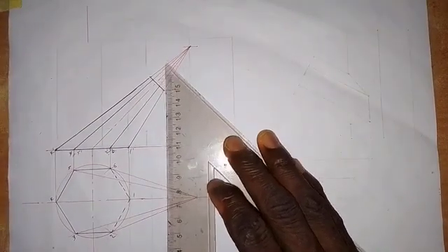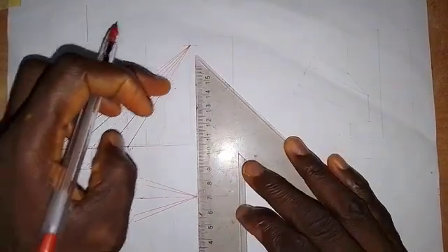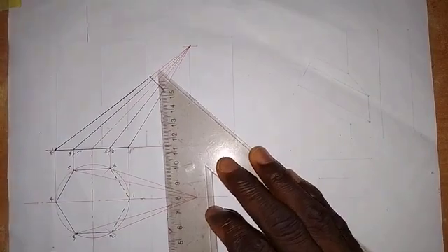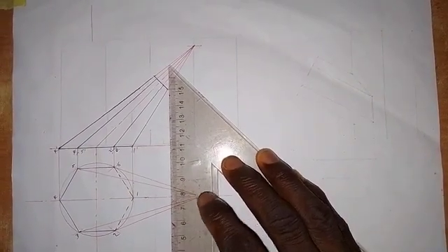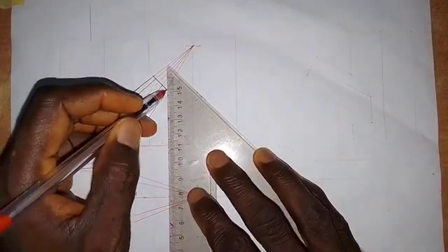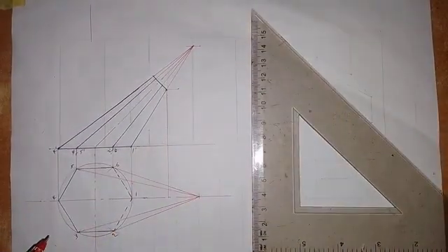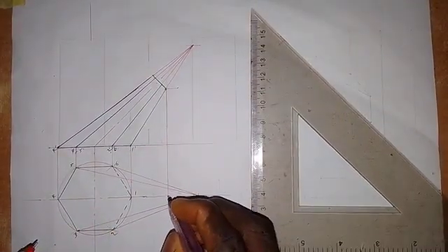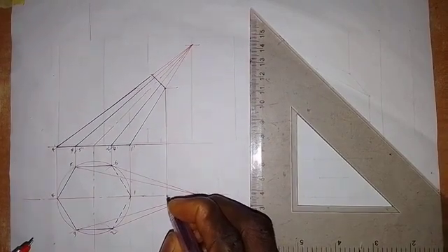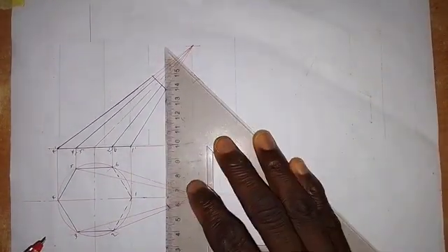For the complete plan, because we are going to have a raw surface here, and they want us to have it in the plan, that's why we need to draw a vertical line from this point down to the plan. So it touches line 1 at this point. I will take note of this point here. So this is point 1 in the plan. Then we have 2, 6.